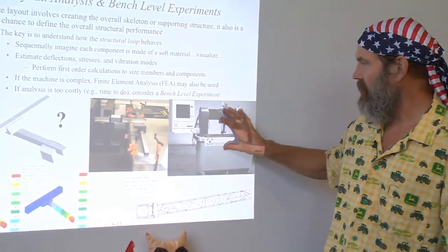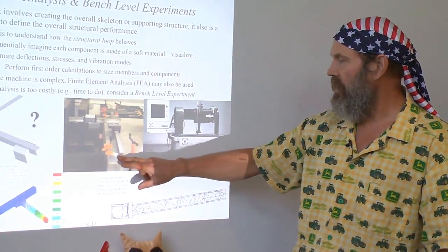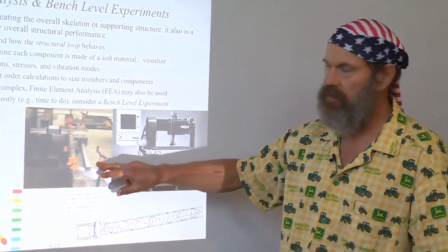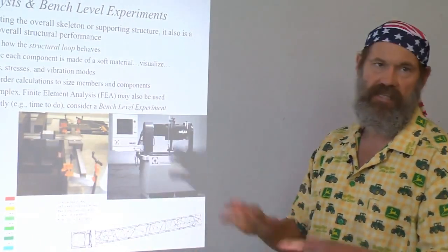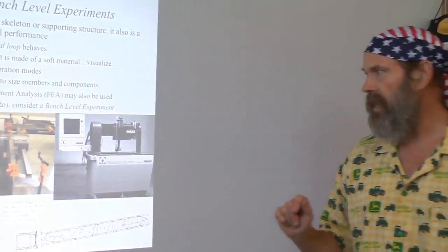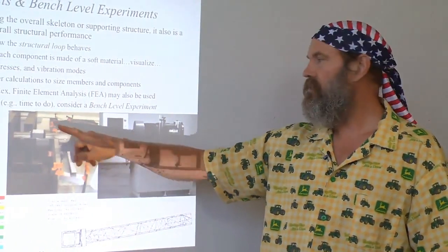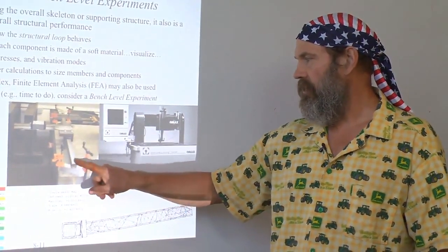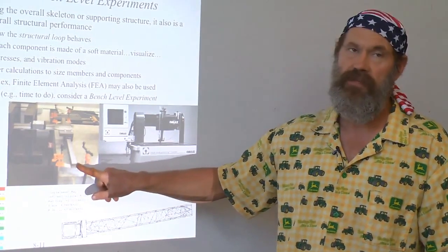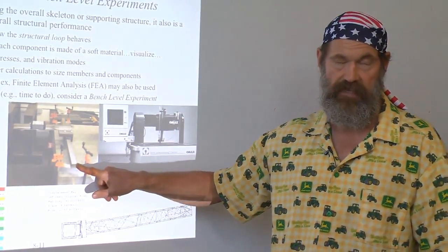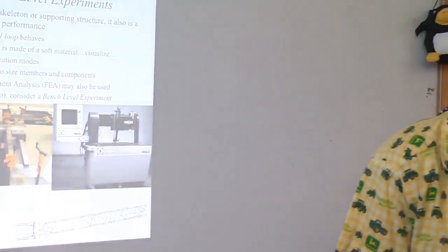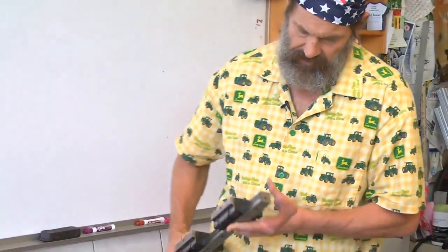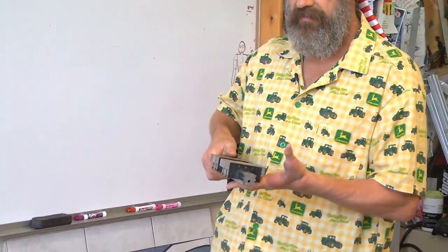for a small machine? Can we take really giant, way oversized bearings and use the bearing block and the rail itself, and that's it? It turns out you actually can do that, and you can afford to do that, because some of these large bearings, this is a size 55 it's called for linear guide bearings, that we'll talk about when we talk in topic 10 about linear bearings. This one here, by the way, I believe was a size 35. So 55 is that much bigger.